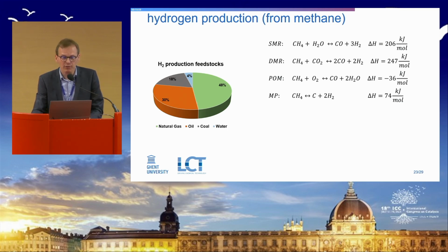Now, given the presence of the CO2 in the biogas already, given the stoichiometric target that has been set, in fact, the hydrogen contained in the methane is just sufficient to hydrogenate the CO2 which is in the biogas. So to that extent, producing more CO2 is not of an added benefit on the scale of the Obi-Wan project. And that is why methane pyrolysis has been the method of choice to focus on.